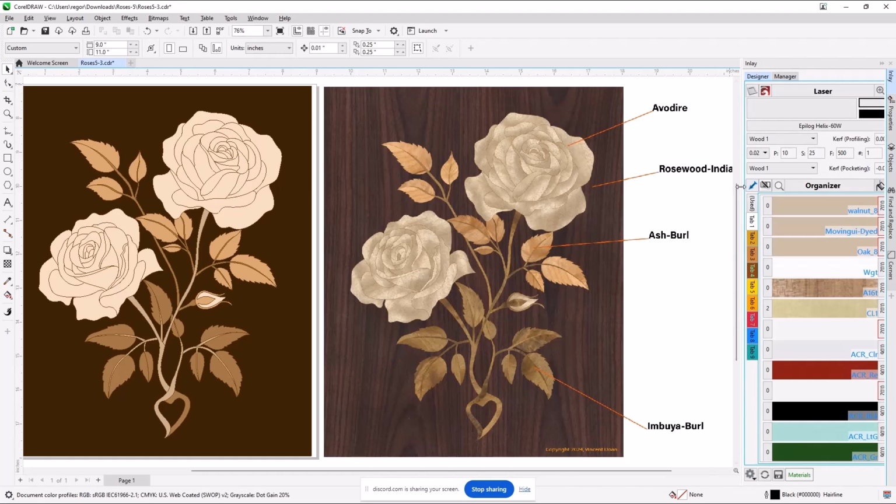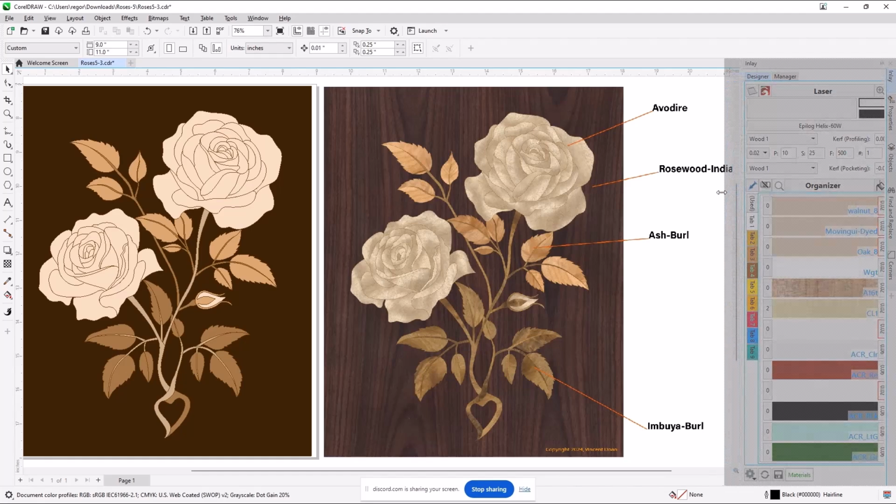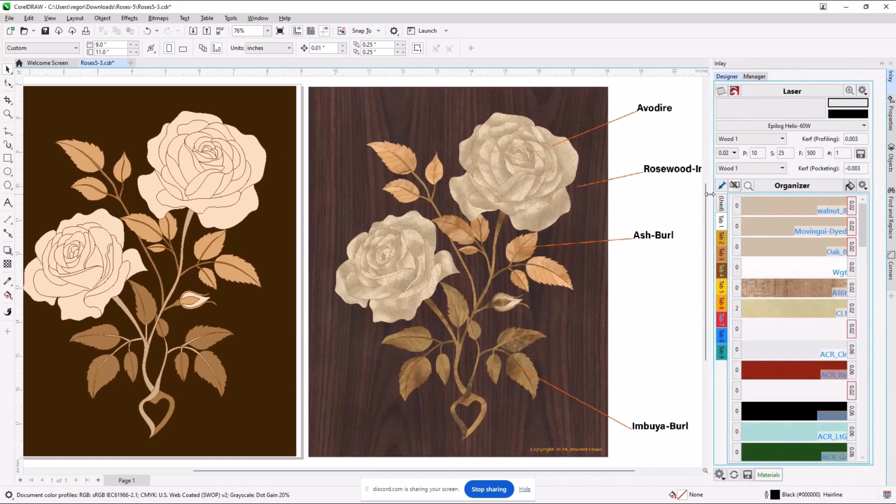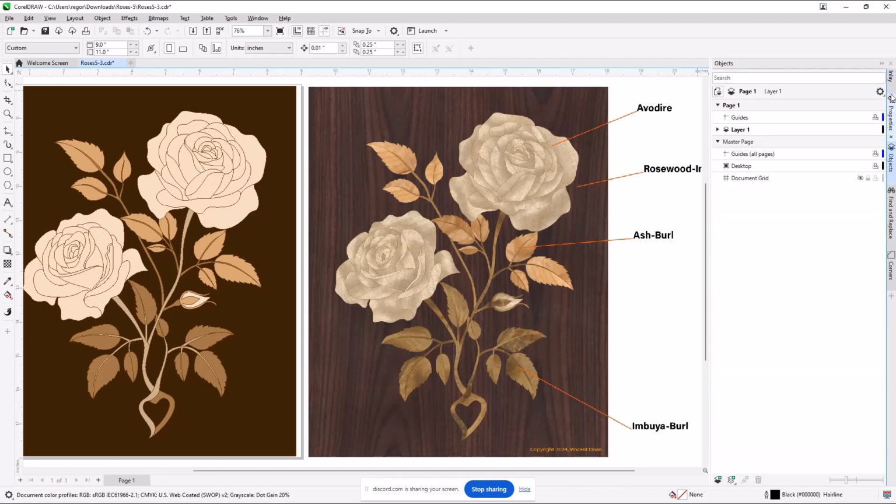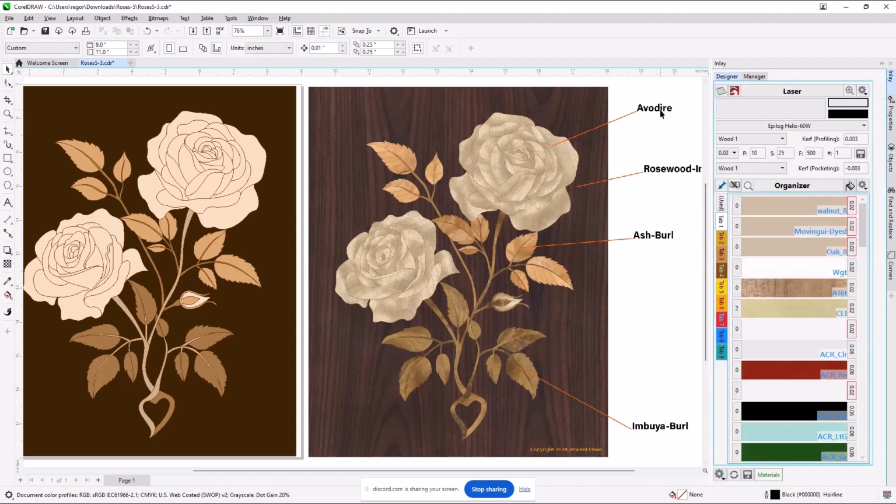One of the things that you would like to do, I don't know how many of you have more than one monitor, but it's possible to take any of these panels and drag and drop them out of this drawing area to a separate monitor. So when I'm working, I may well have taken the inlay panel and the objects panel and put them on my other monitor so I don't have to pop one up to get to the other and back. I can keep them both visible and active.